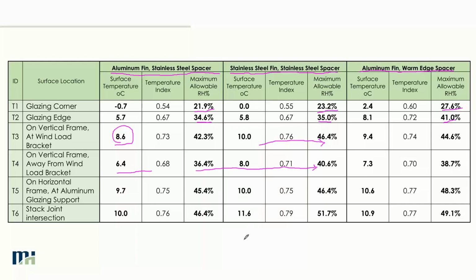And in a lot of cases for condensation, you may just want to hit certain thresholds, right? In this case, we know maybe they're trying to maintain the spaces at 40% relative humidity. So as long as we can get something up to that level, that may be what they need to hit that threshold and be comfortable with it. You know, it may be not a huge, earth-shattering improvement, but at least it gets them to where they need to be in their design, and that's enough.